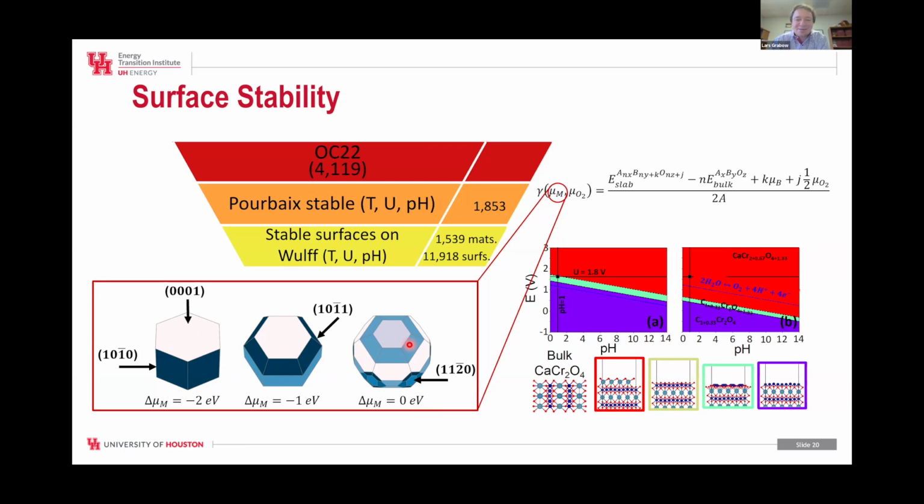That's essentially what we're talking about here. So the HCP crystal structure has planes of very low surface free energy, and those are the ones that end up forming these nice hexagonal shapes. But for many other crystal structures and geometries, you'll find different shapes, obviously.